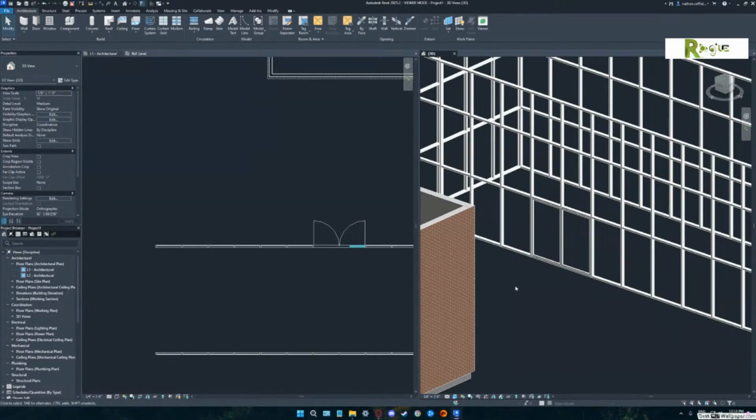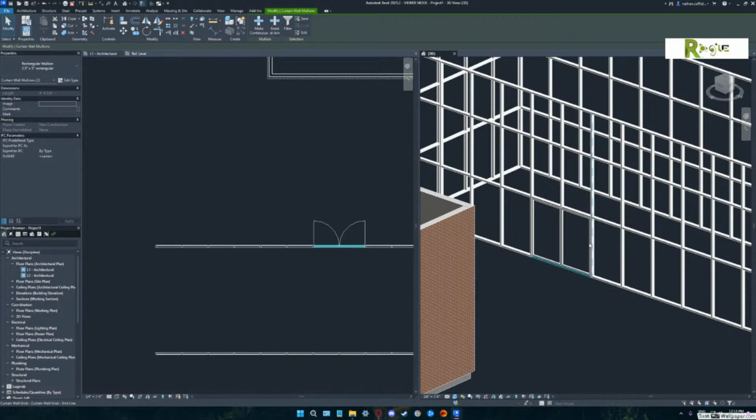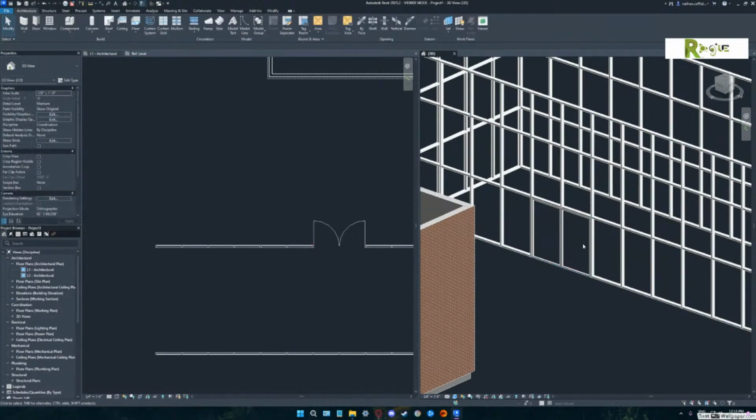What are you doing? Escape 2 times. Don't move your cursor. Escape 2 times. Okay. Now pick and drag. Other direction. Go. Keep going. Look, you got those 2 mullions. Okay. Right? I got you. And now you could hit delete. And now that door would go to the bottom, and in plan view, it would look correct.